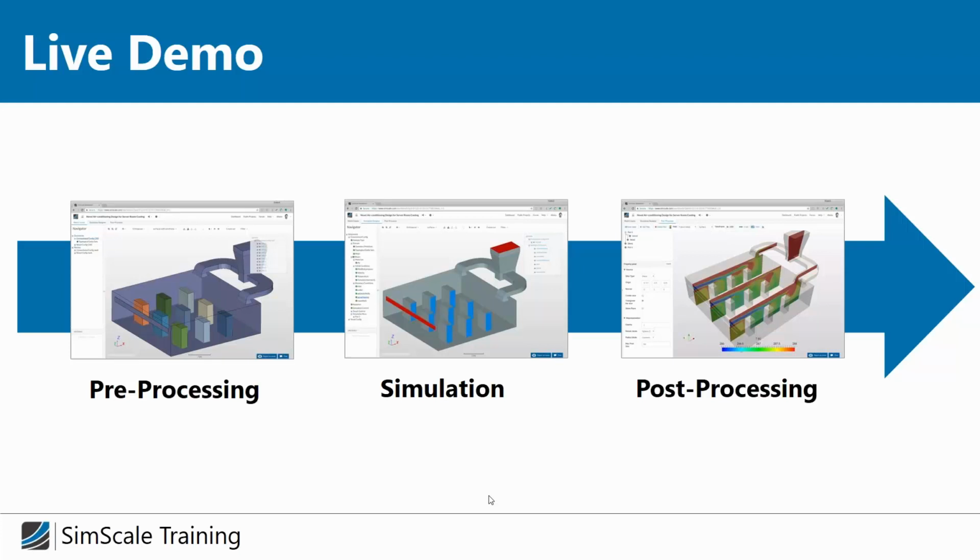The first part is about cleaning and preparing your actual CAD model, which means you need to make sure your model is watertight. You should take care of cleaning up the model as much as possible. This means removing very small surfaces or intersections and really making sure the model is clean from a CAD perspective.